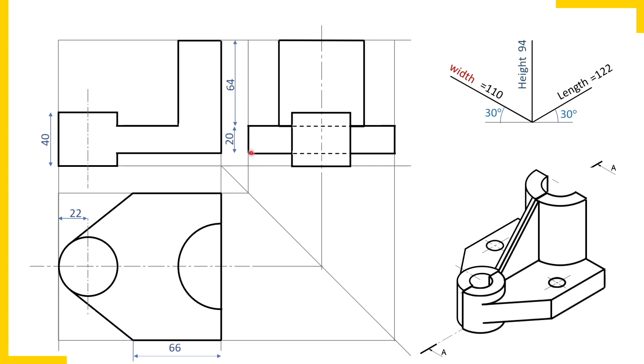If I ask you where is that horizontal plate in the side view, show me this entire rectangle. Simple. But now you will have to think about the joints. Now, where this plate meets the curved surface here, it is a tangential joint that is to be shown here.